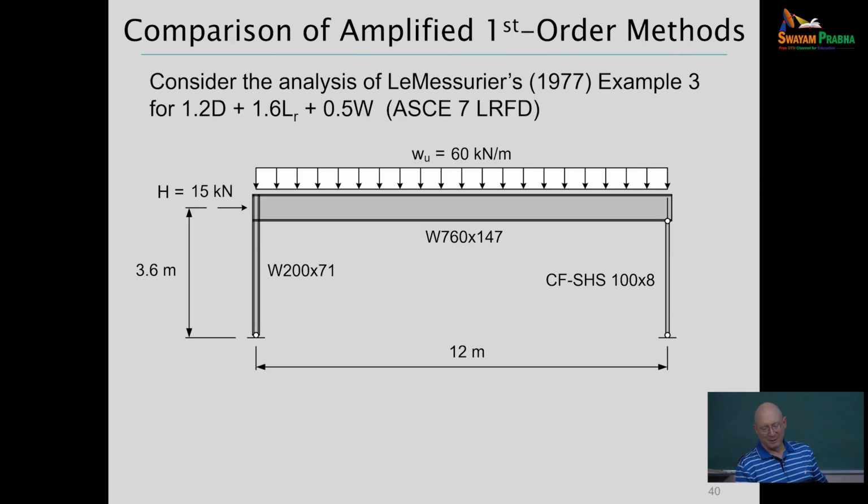We've got a reasonably lightweight wide flange column on the left, a reasonably deep roof girder on the frame, and this market shed, so to speak, on the right is the storefront, so we have a very light HSS column there, and we're going to idealize that as a leaning column in this analysis.